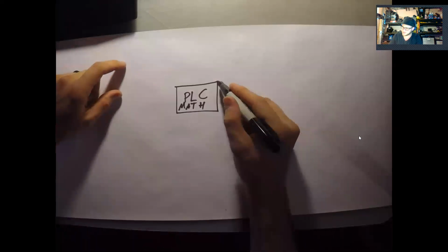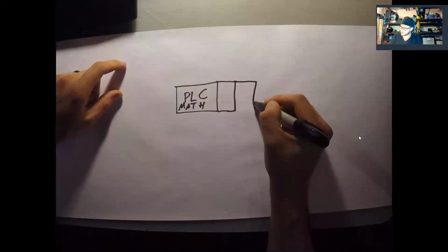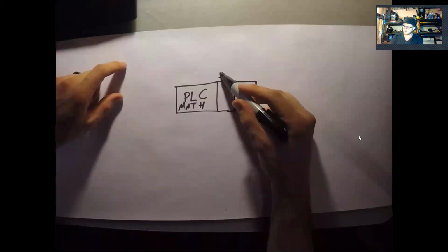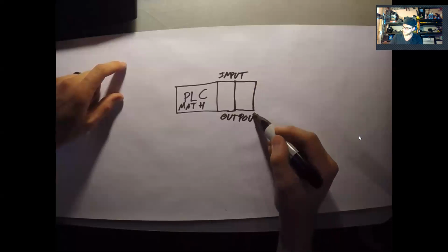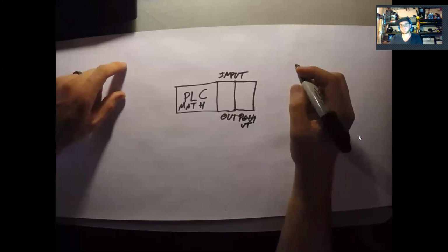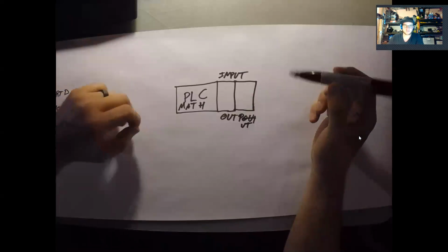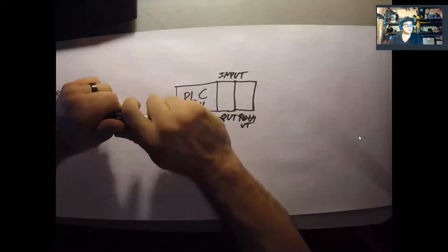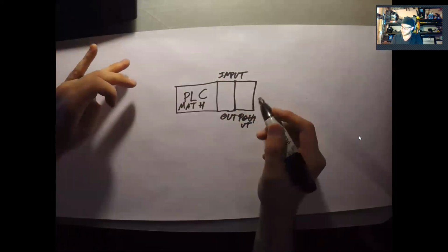And on this PLC, there are these auxiliary modules that you can just clamp onto the side that are your I/O, right? They're your inputs and your outputs. So you can buy all different kinds of I/O modules, depending on what you need. You can get relay contacts, you can get all different kinds of voltages. There's all kinds of things that are industrially available.